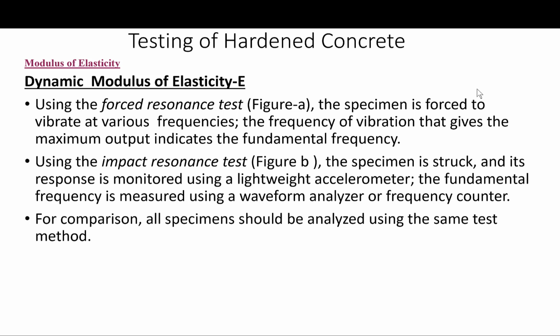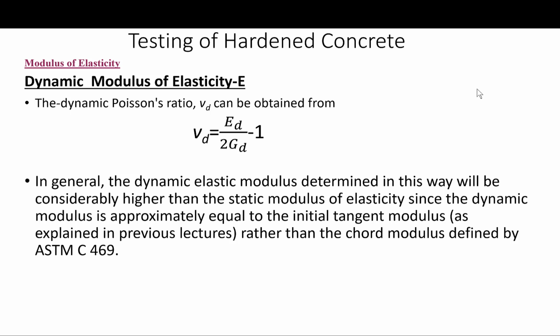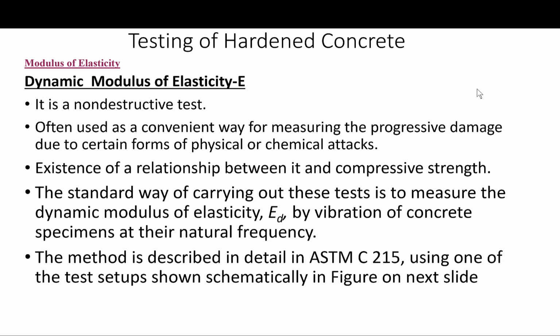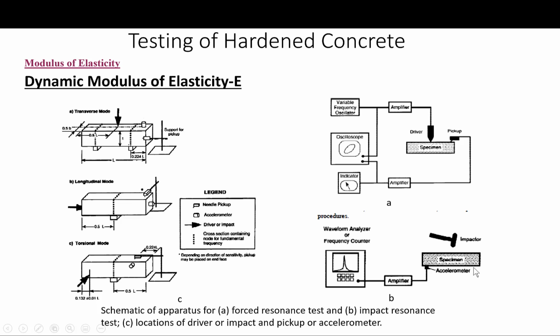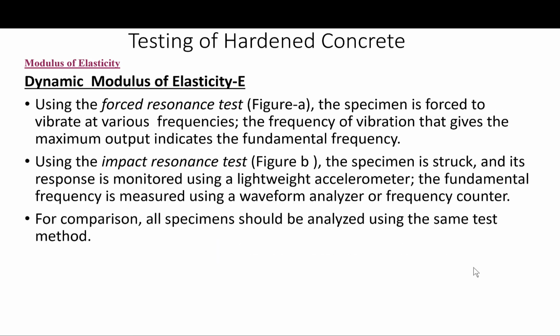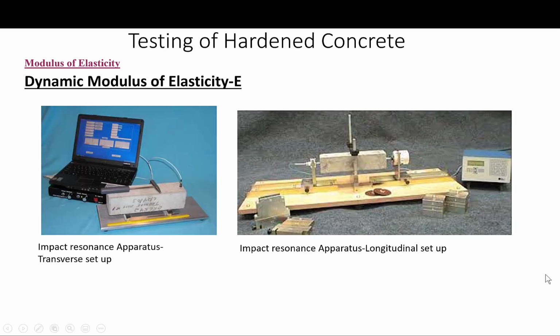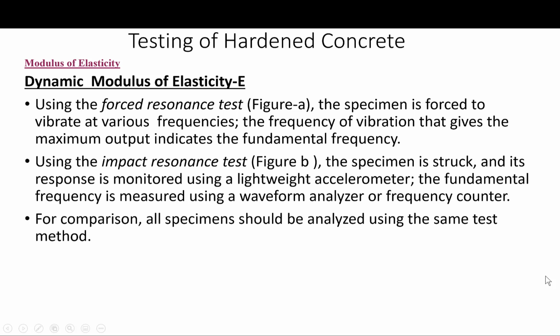When using the impact resonance test, I'm sorry, let me go back. This one here is the setup for the impact resonance, okay? The specimen is struck and its response monitored using a lightweight accelerometer. The fundamental frequency is measured using a waveform analyzer or frequency counter, some of these devices, okay?